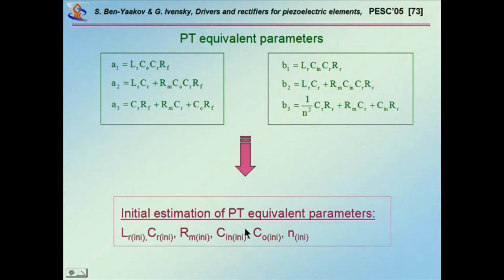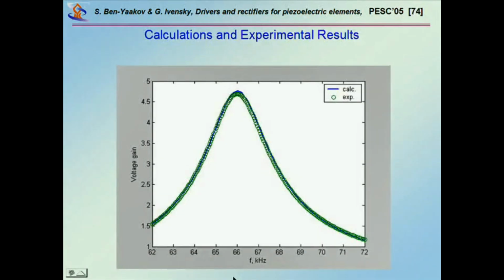And when you do this, from the parameters, as I showed you before, you can extract the parameters of the model and eventually end up with a model which is very, very nicely fitting your transformer over an extended area under the real excitation. Okay, this will be under, say, a few hundred volts or whatever that this transformer was designed for. Yes, please.